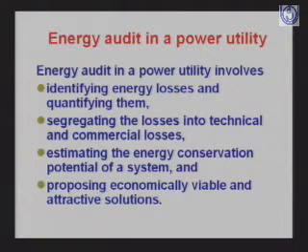Coming specifically to power utilities, in a power utility, energy audit means identifying energy losses and quantifying them. Basically, in layman's language, energy audit is energy input output analysis. When we take into account the energy input and we take out the energy output, what balance is left is the losses. So these losses, or wastages, are to be attacked, and this audit will help us in identifying such losses and the areas or energy conservation measures to be effectively implemented to reduce such losses.